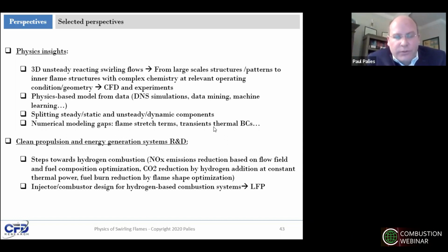What I call fully premixed combustion is that you have a liquid fuel that is brought to an injector, but it has a heat exchanger piece which converts this liquid fuel to a gaseous fuel. Then it's mixed with air, and it creates the premixture of your premix flame. As of today, you do not have this type of heat exchanger implemented.